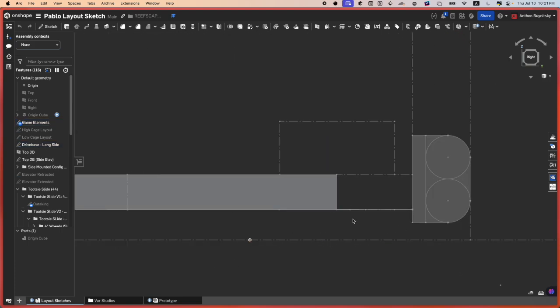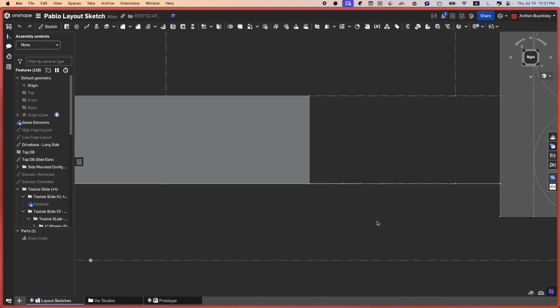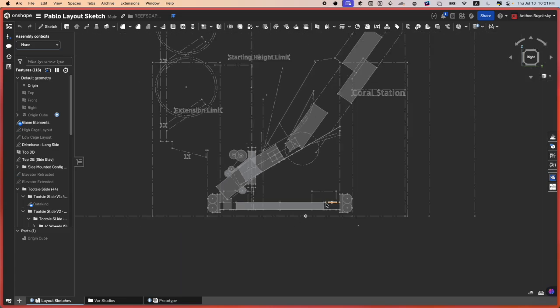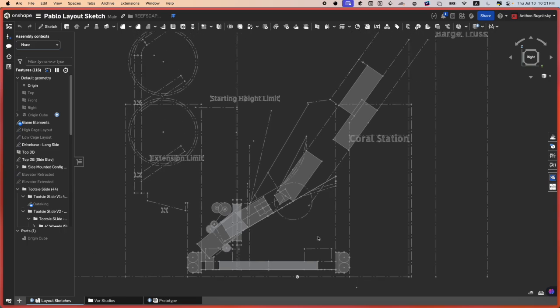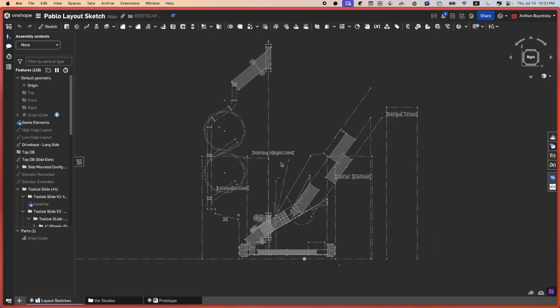As you can see, there are absolutely no wheels here at all, and if I made some wheels, it would literally just be a circle. So I would say the top features used when layout sketching will be circle, rectangle, and line. You really do not have to use anything else, like hole patterns or anything like that. So really try to stick with those three features.